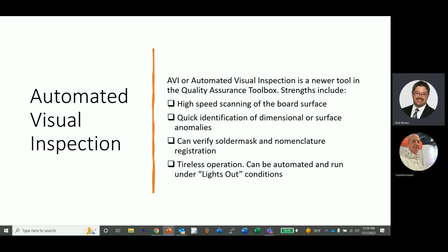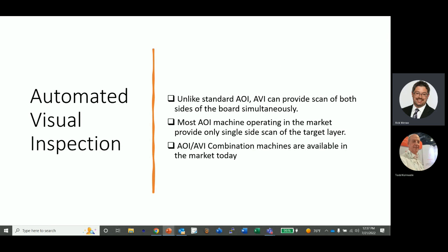So the CAD image is usually, let's call it, a black and white image, so you know where all the features are. And then when you do your first scan, you're going to find out the colors of those features. The colors of the features are what's used, once it's set up and tuned in, to pick up any inconsistencies in future boards. It's like the first couple batches or boards that you scan, you may have something wrong with the first one because we don't have a known good one color-wise. So then you may have to come back and look at the colors and just retweak a couple parameters. But more or less, it's looking for that.